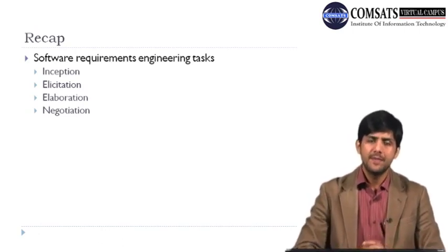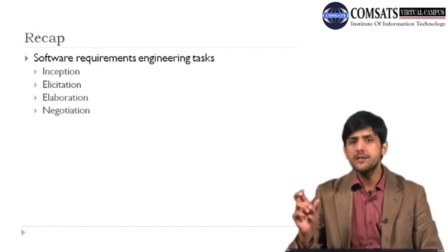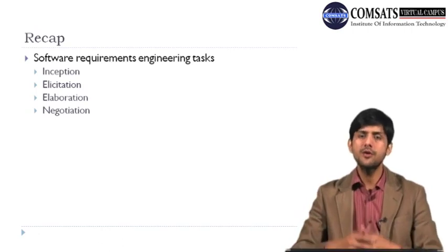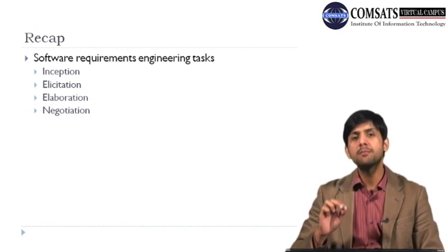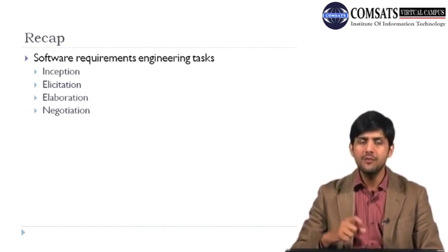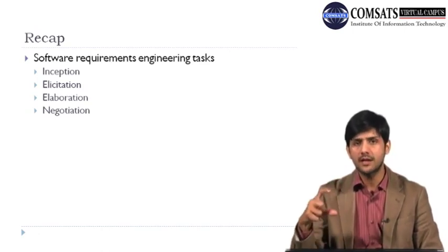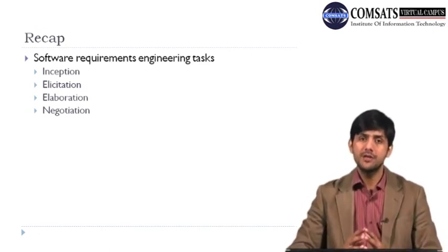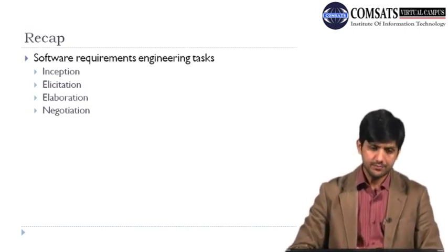We also decide which technical features we want to give more priority to. Another interesting thing about quality function deployment is that you can also rank those technical features, and you can do a competitor analysis as well. For example, you have a competitor out there and you're making a product and you want to evaluate where your different competitors stand on a technical feature. And obviously when you're developing something, maybe you want to give more importance to a certain technical feature, and then the development effort would be estimated accordingly. For example, if you want a technical feature more strongly, then more effort would be put on that in comparison to the other technical feature.